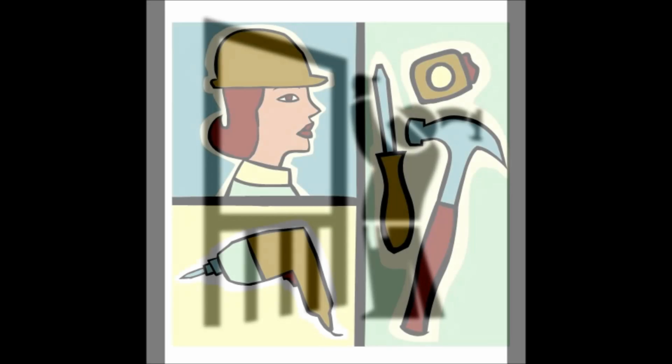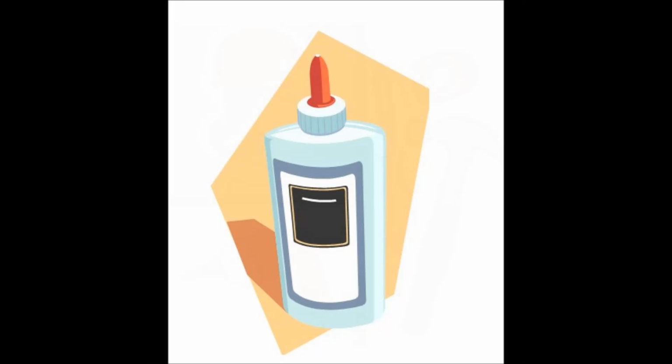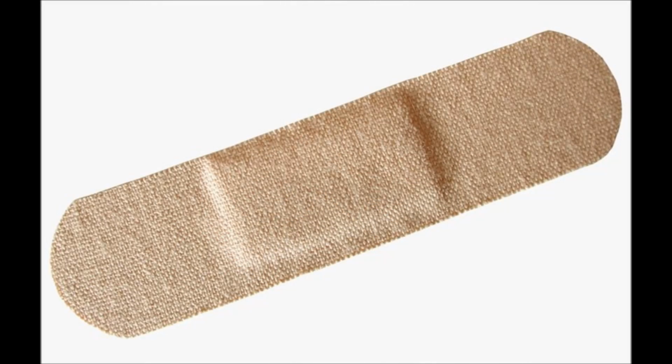the pieces. Magnetic shielding plates and foil can be fixed in place with nails, staples, screws, glues, rivets, or any other suitable mechanical means that will support the weight and prevent annoying vibrations or shifting. Small perforations due to a few nails or screw holes will not significantly affect shield performance, unlike radio frequency shielding. Remember, the shields will be attracted to the magnetic field, so plan for supporting accordingly. Exposure of sharp edges should be avoided to prevent injury from contact.